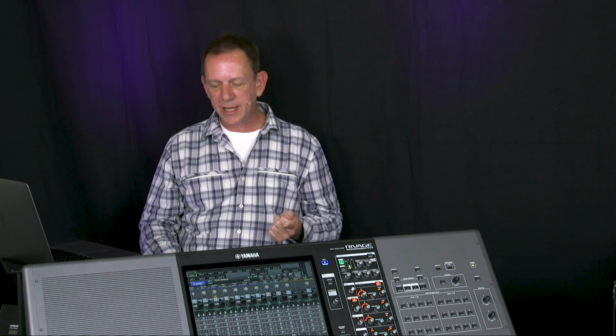Right, running out of time, but I'll try and get a few more questions in. I think we'll answer this question: can I use cascade mode, which we don't use anymore, with 2 DSPs to increase the amount of input channels? Yeah, that's a good question, and true, we don't use cascade mode in Rivage systems. If you have a DSP R10 unit already, perhaps with a PM10 system, then you are limited with 144 input channels.